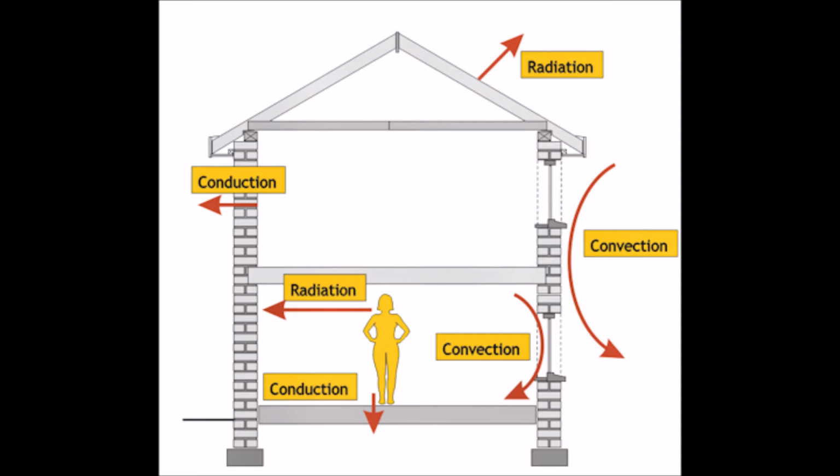This anomaly allows us to categorize thermal radiation as short-wave solar radiation and terrestrial or long-wave infrared radiation. Surfaces in the built environment will tend to absorb solar radiation and emit long-wave infrared radiation. This difference also produces effects such as the greenhouse effect.